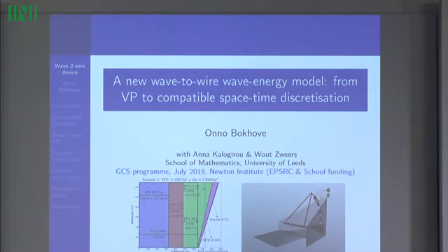And then on the buoy there is a mast or an arc. There are coil magnets here, and the magnets go through a series of coils. And the coils, this is the green and the red, they are the loads. The coils are connected to the loads, and they're indicated here in green and red. And those are LEDs, which is just because it was a simple description as a load. And the LED only works when the current goes one way, and therefore they're in parallel, so that when the current goes the other way, because the motion goes up and down, so it changes directions, there is always energy generated, and energy here is generated in terms of light.